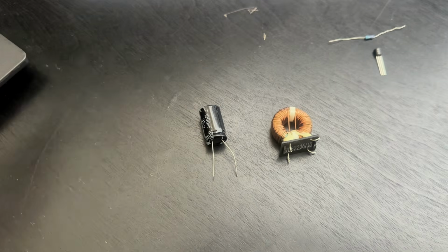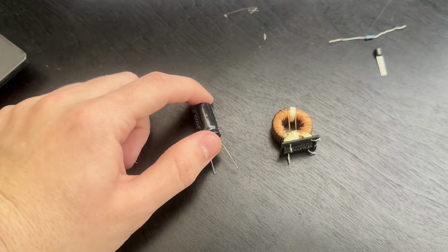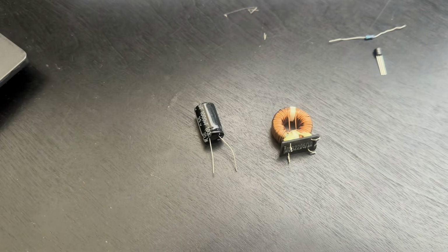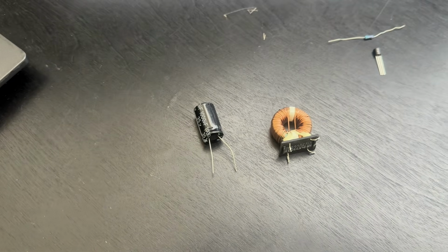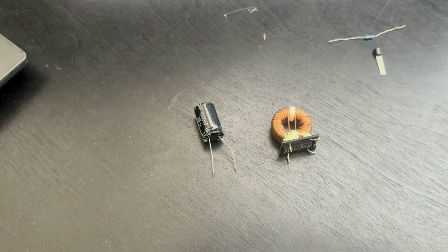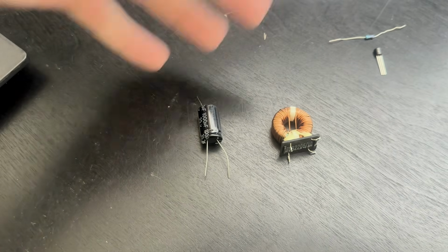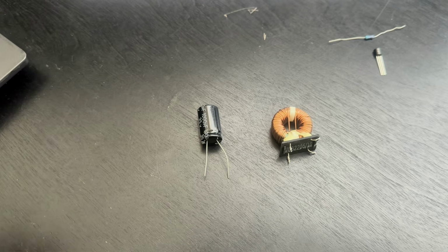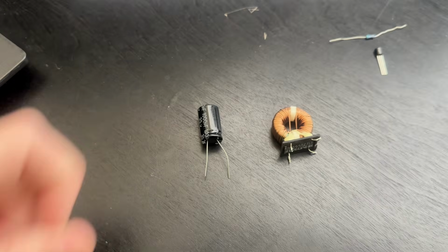And this could be useful for some circuits, like if you want a circuit to release a pulse for a second, you could use a capacitor because eventually it's going to act like an open circuit, if that made any sense. And then you can combine these two together to make oscillating circuits, to make different timer circuits, to make an astable multivibrator, which is what I use again in my transistor clock to make a kind of pulsing circuit. But essentially, these are just energy storage devices. So you can store energy and release energy within your circuit. And that's the basic idea of how these 2 components work.